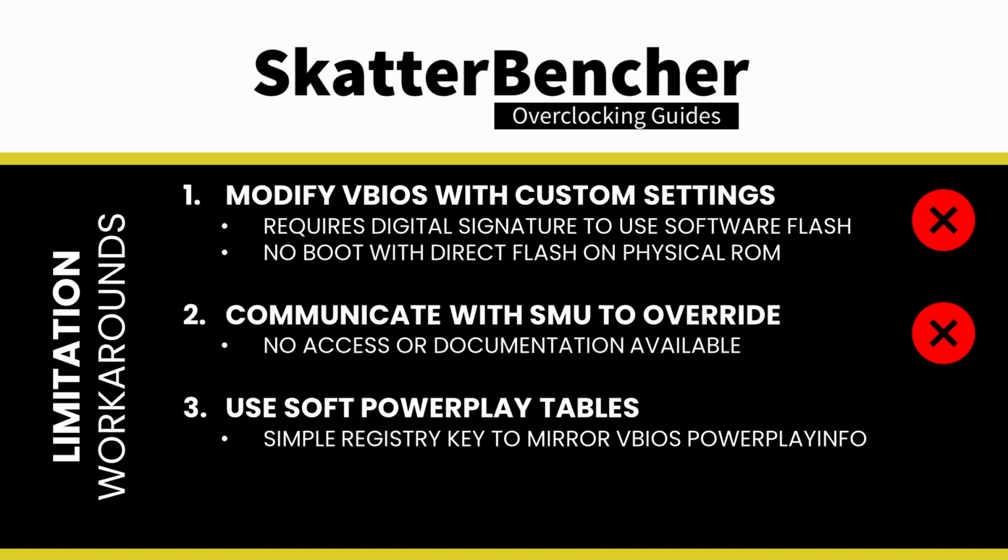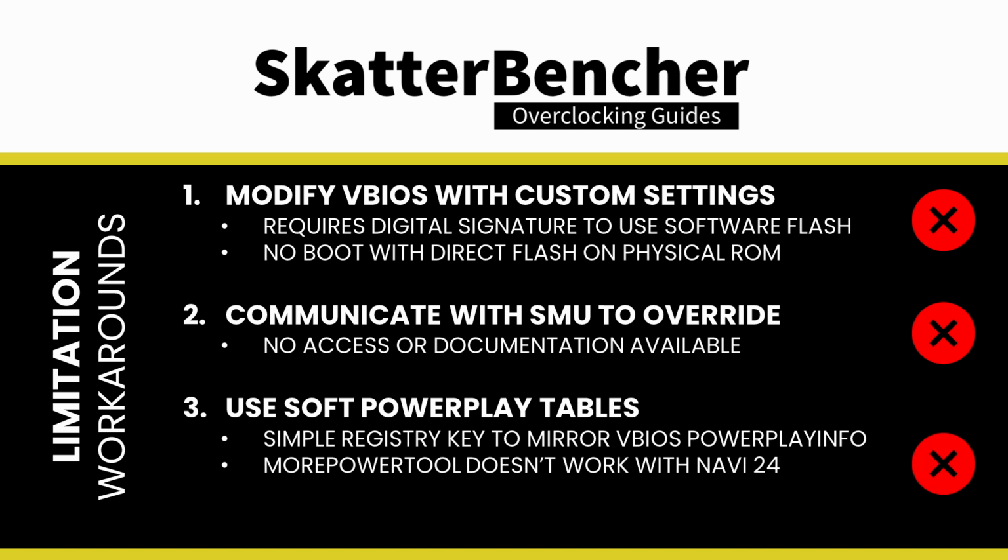The most user-friendly approach is using MorePowerTool, which enables users to customize the registry entry with their settings. Unfortunately, MorePowerTool doesn't work with the Radeon RX 6500 XT because the PowerPlay info module for Navi 24 has a slightly different structure than prior Navi cards.